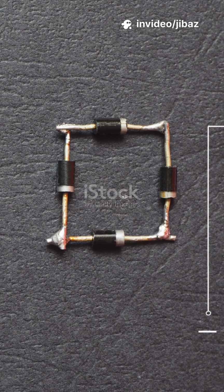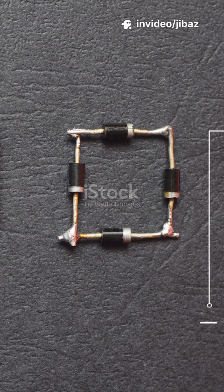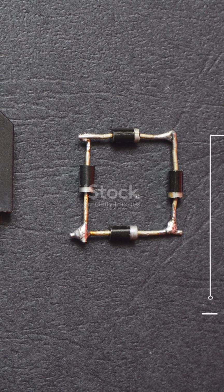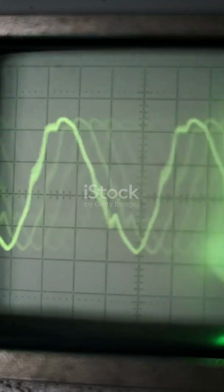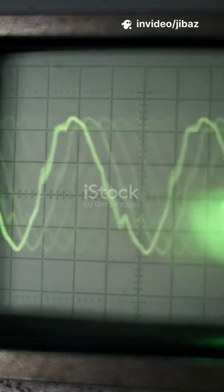In the simplest form, a half-wave rectifier, we use just one diode. During the positive half cycle, the diode conducts and allows current to pass. During the negative half, it blocks current, leaving the output zero. The output is pulsating DC, one half of the wave. Simple, but inefficient, since we're wasting half the input power.